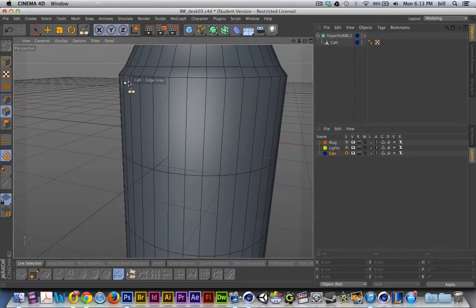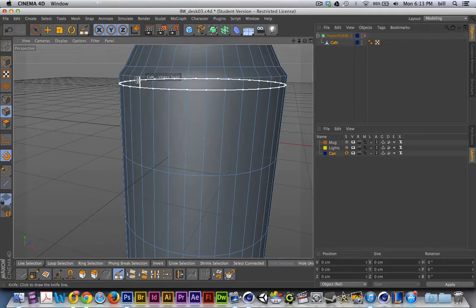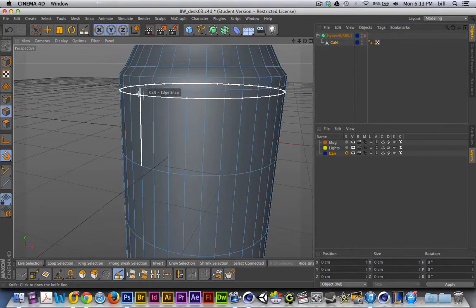So I'll tap the K key, which will bring up the knife tool again. Once I select my geometry, I'll start seeing that loop. It's still in loop mode, so I'm just going to click. And I didn't quite get that exactly where I want it, so I'll undo.